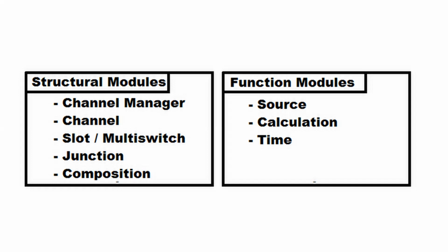The slot multi-switch modules. I call it a slot, some people call it multi-switches. The idea behind them is if you add one, then more slots to one channel, it performs a multiplexing on that channel, and on every cycle you can access a different actuator, which can be an LED, which I'm going to show you, or it can be a servo, whatever. But if you only use one slot, it doesn't have any impact.